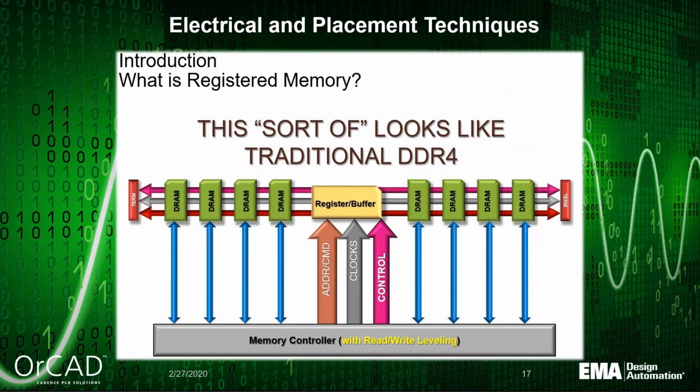Now, memory controller with read-write leveling and registered or buffered placement now takes on a different need: that of having the termination at the end of each DRAM bank. This is what you will see in the demo that I'll be doing later on. Termination could also be built into the device, as Jerry pointed out.